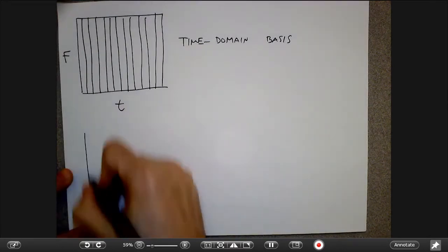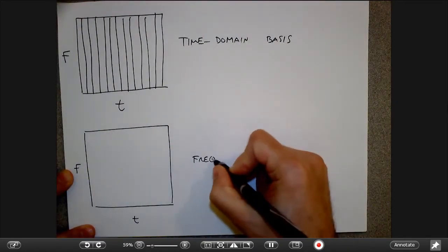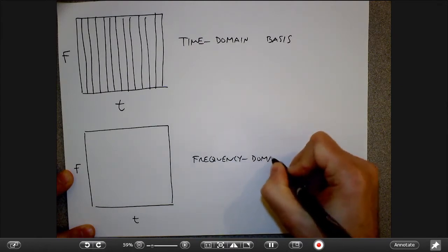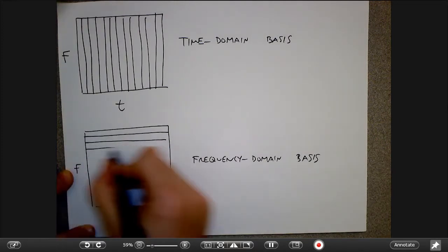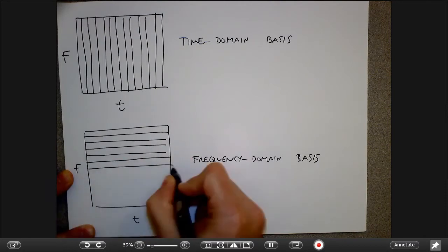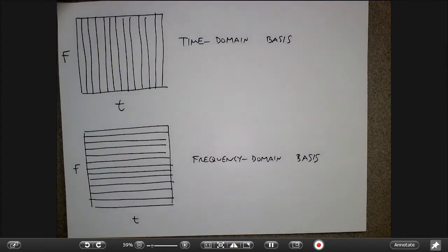So then we talked about the frequency basis, right? So a frequency domain basis is more like this, where now I can ask you to tell me the frequency content at a fine set of frequencies, but each of those coefficients corresponding to one of these rows tells me about a sine wave that is spread out across the whole time domain spectrum. So there's no temporal resolution in a Fourier transform, right? I only get frequency that corresponds to the content across the whole signal, right?